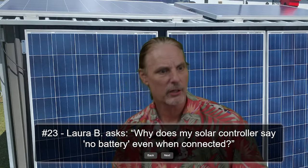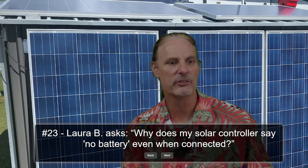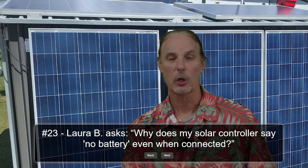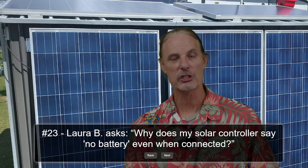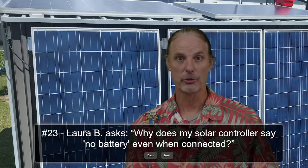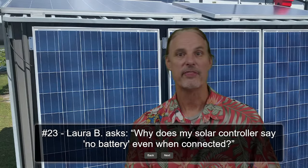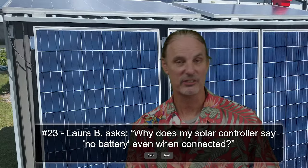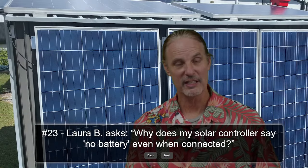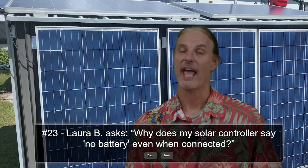Question 23, Laura B asked, why does my solar controller say no battery even when it is connected? Chances are you probably have it set for closed loop, meaning that you're supposed to have communication cables connected from your inverter to your battery. Your batteries are supposed to be connected to each other through this communication cable, and that would send over the state of charge. My 6000XP has this problem. When I have it set on closed loop and I disconnect that communication cable, it assumes there's no battery there, even though it registers the voltage and I have a full battery.